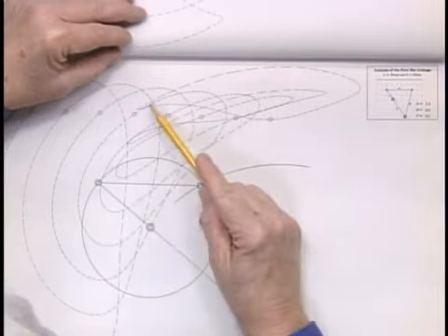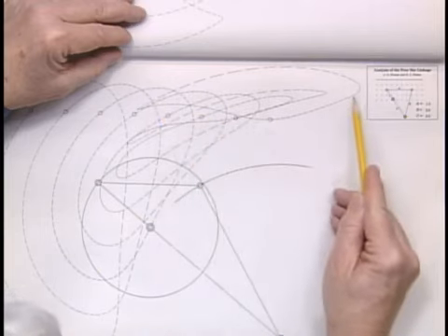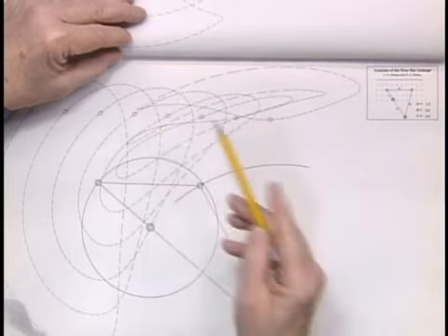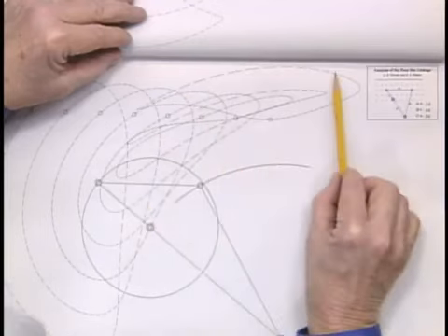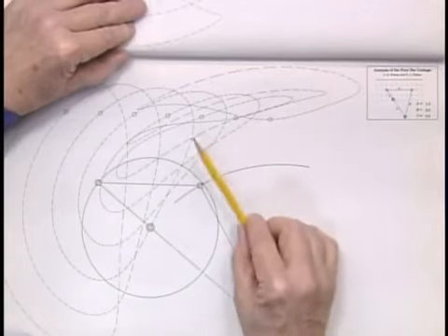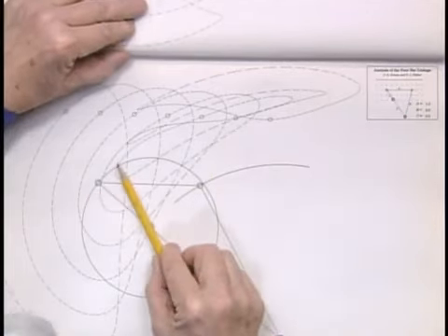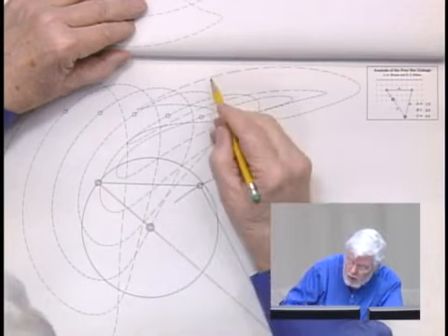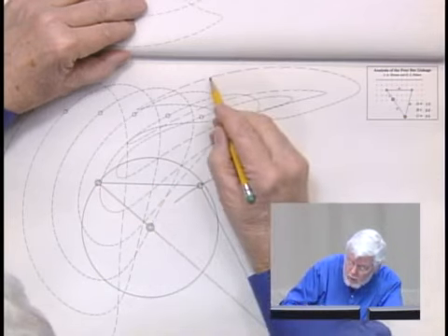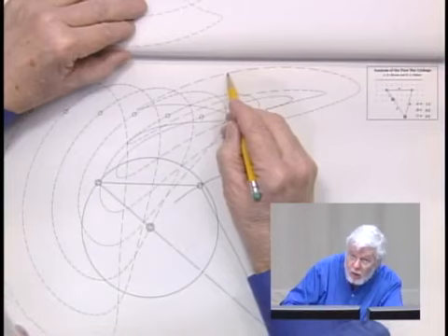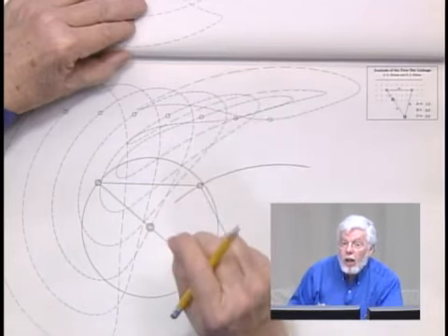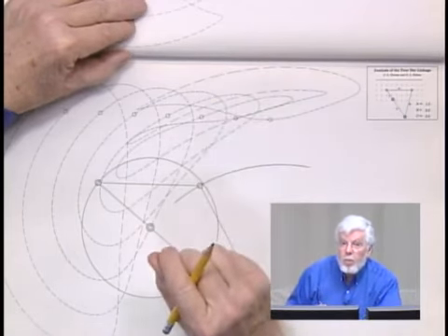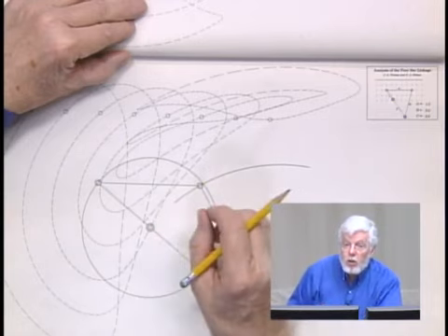You'll notice that these curves are all done with dashed lines, not with solid lines. And the dashes have meaning. Each of the dashes that you see on any one of these coupler curves represents exactly 5 degrees of crank rotation. Actually, to say that more correctly, the distance from the beginning of one dash to the beginning of the next is 5 degrees of crank rotation. Now think about that. If I'm turning the crank at a constant speed, then equal angles are equal time.